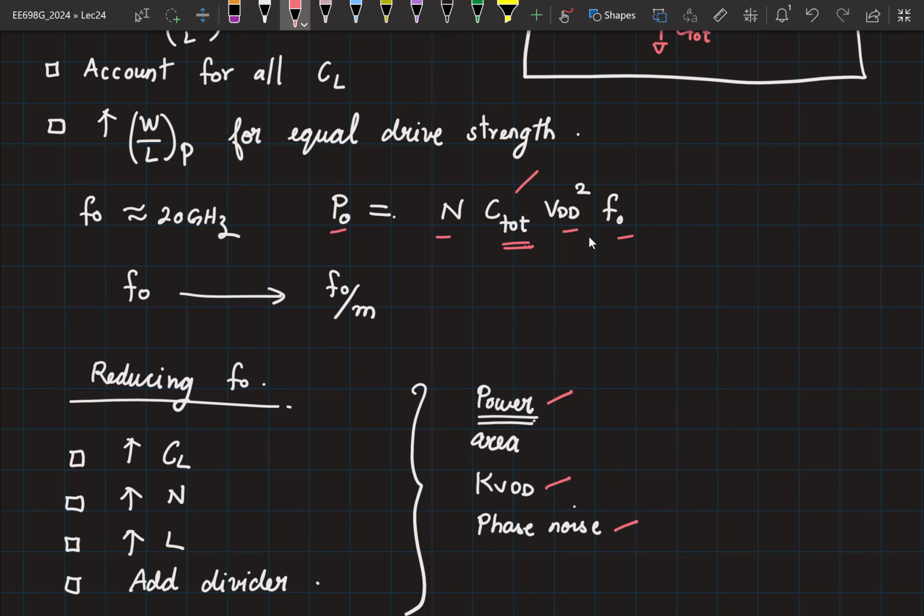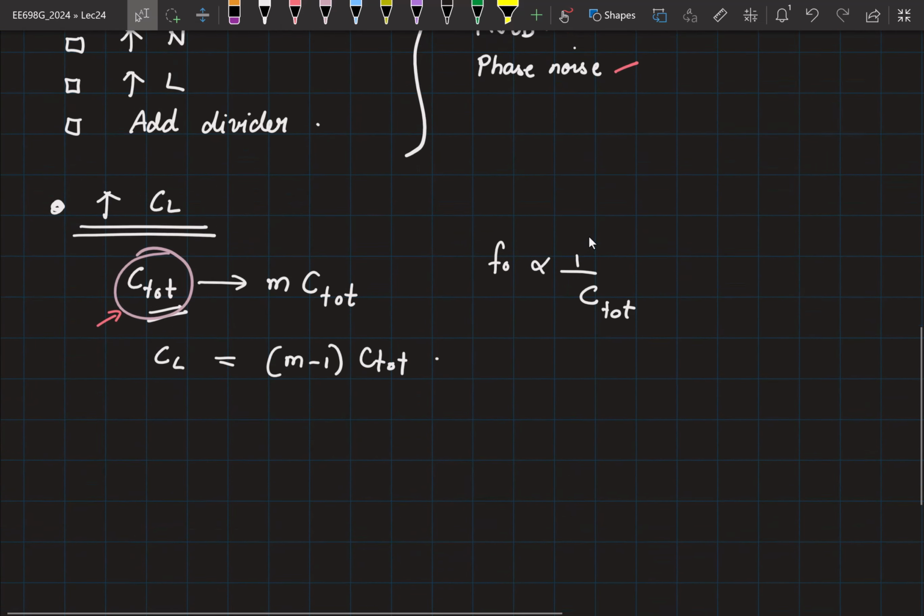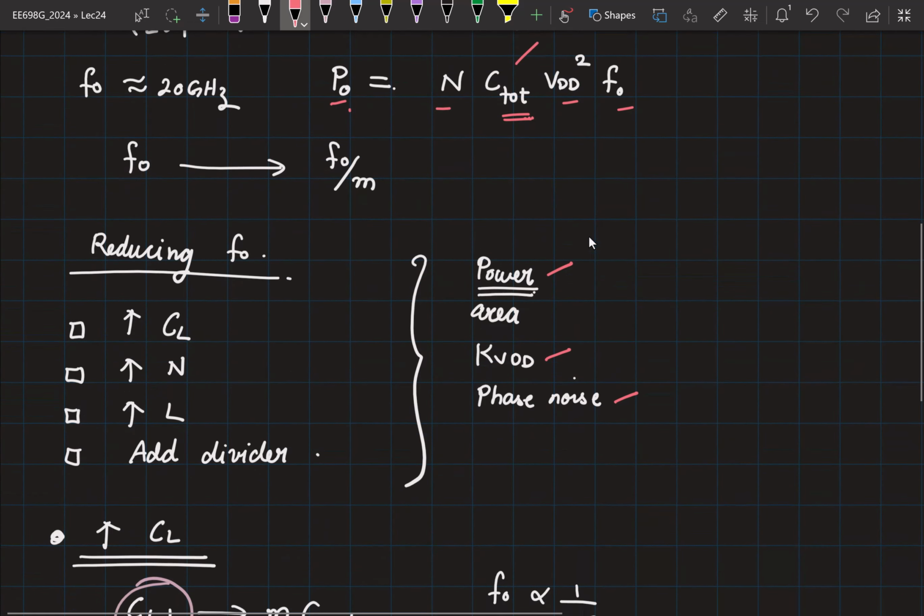Correct. So your power, when you run a simulation, you will also measure the short circuit power as well as the leakage power. Leakage is usually very small, but short circuit is going to be slightly higher than leakage. Still, you expect it to be smaller than the dynamic power, but all of these are going to affect the estimate of C total you get here. Okay? So, for a quick approximation, you will get a C total value here.